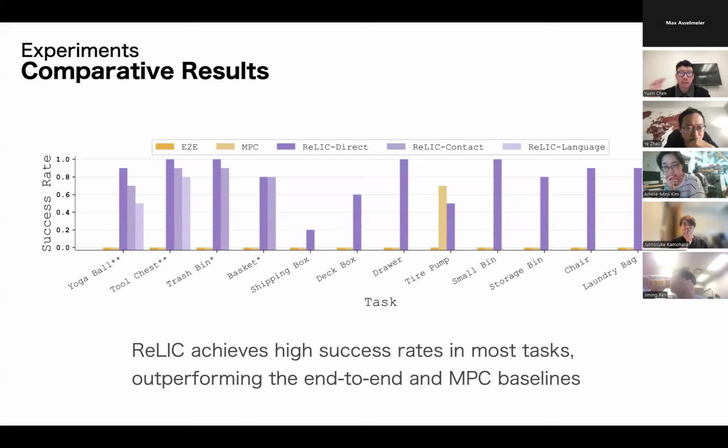And if we focus more on the manipulation success rate, then the robot may not actually move. It will just tend to stay there, or whenever it moves, it will just fall down. And the MPC is the embedded controller by Boston Dynamics, and it doesn't have the feature enabling additional leg lifting up. So their policy can only support 4-leg locomotion.